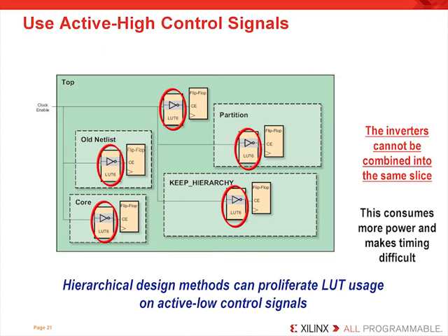Now, if your design is not going to use a high percentage of the device, usually less than 70%, this will run at modest speed and does not consume much power, then following these guidelines may not be as critical. But if you have the time to build the design properly, which we really encourage everyone to do from the beginning, and you're not sure about your device utilization, you should take the time to build the design properly. Now, in case you're not familiar with partitions, they're supported by the Xilinx implementation tools and allow a designer to maintain parts of a place and route solution. This allows the designer to verify and maintain the results.